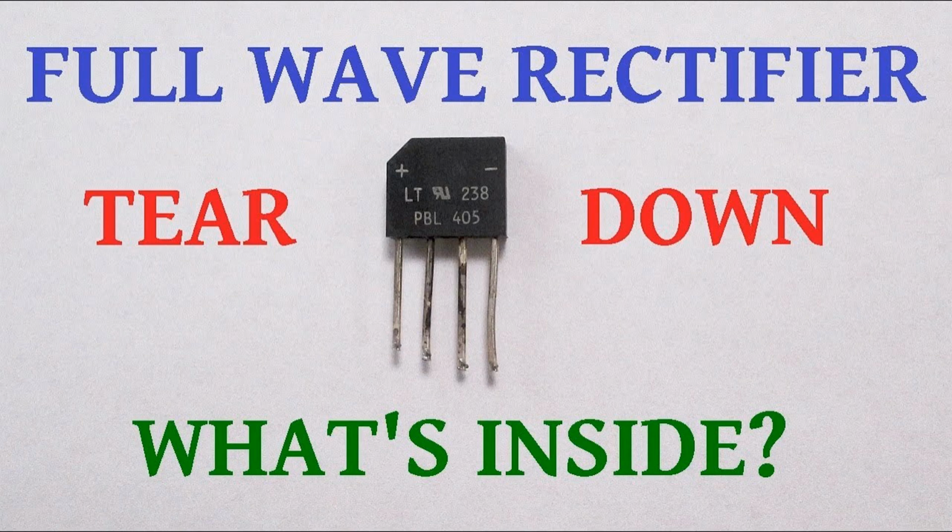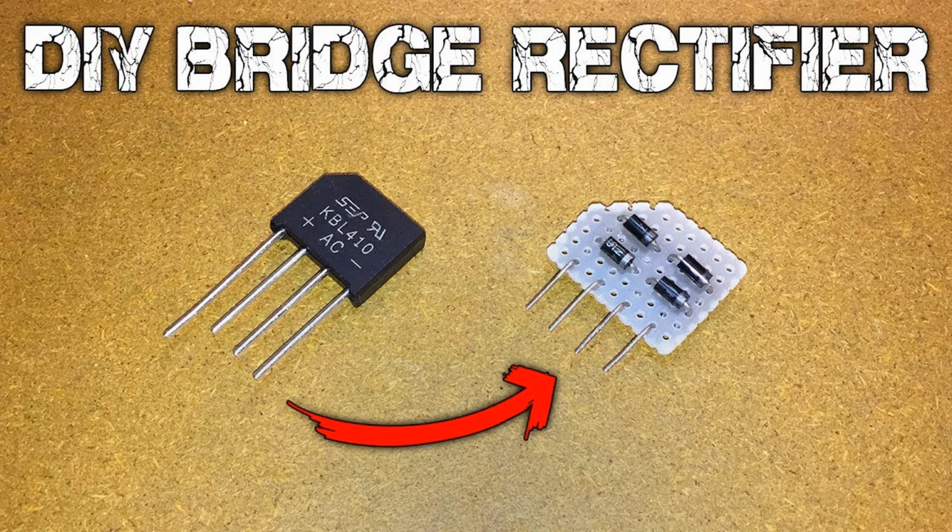Variable frequency drives, VFDs. Bridge rectifiers are integral components of variable frequency drives, VFDs, used for controlling the speed of AC induction motors in industrial automation applications. VFDs convert AC power into DC power using bridge rectifiers, then use pulse width modulation, PWM, techniques to control the frequency and voltage supplied to the motor, enabling precise speed control and energy efficiency.